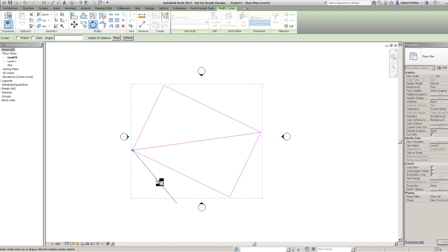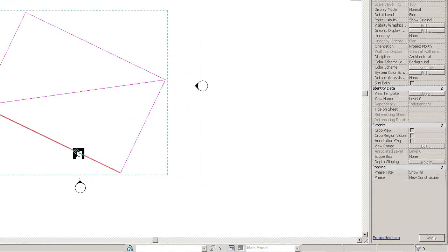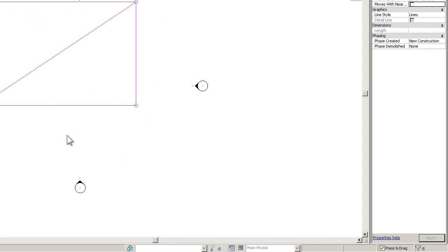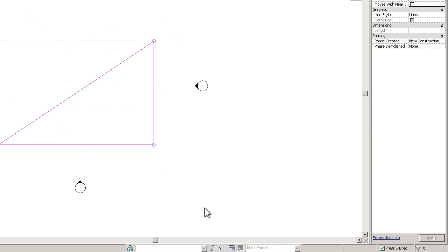Because Revit asks you for your first point of reference, how polite, we can simply click that line just there and choose that to be our first line of reference. Then as we move our mouse around, we can just place it there, completely horizontal. Clearly I must have rotated it around a massively random 25.751 degrees. Left click, that is now completely horizontal again. Fantastic, lovely and easy.